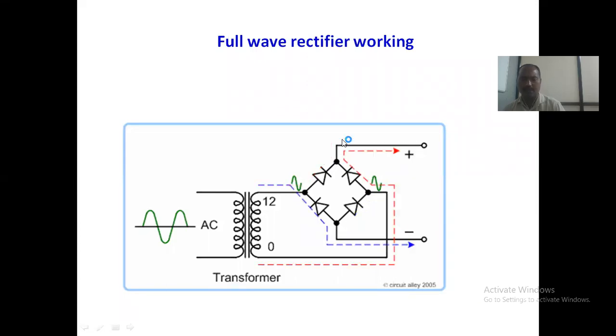There is one way here and another way here, but in this case the diode is connected in the opposite way, that is, the cathode is at the upper level, so it is not conducted. So the positive voltage is coming across here, and that should appear across your output during the first positive half cycle.